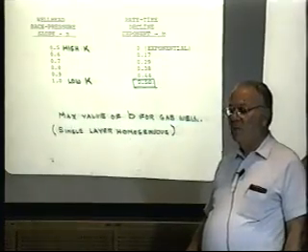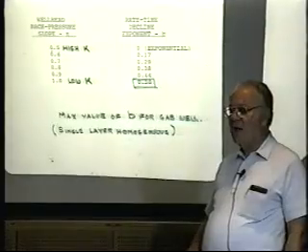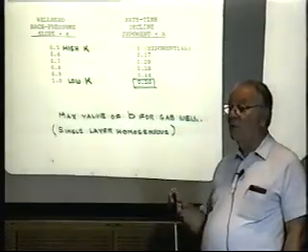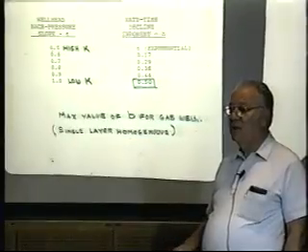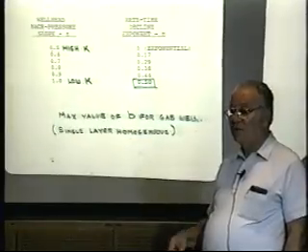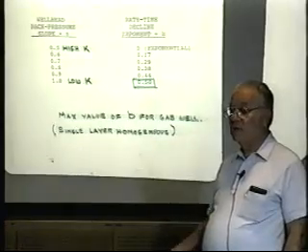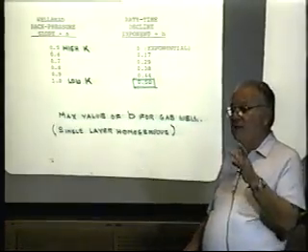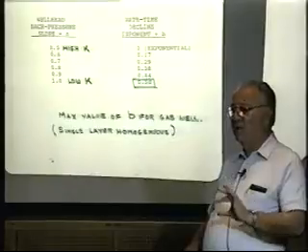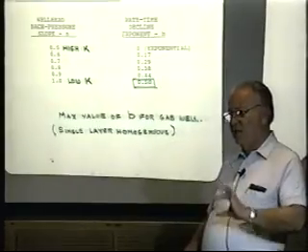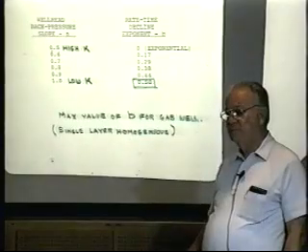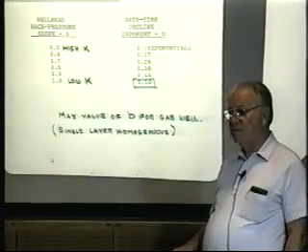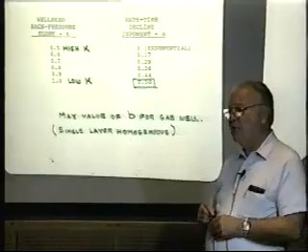And what you can do now to go backwards, what they're doing in Borger, I made this presentation out there a few years ago, and they're making money hand over fist with these ideas of going back to some of these old wells. You're cementing liners in there, perforating, and stimulating by setting bridge plugs, and they're getting big increases in production. All right, how does it apply to Ekofisk?